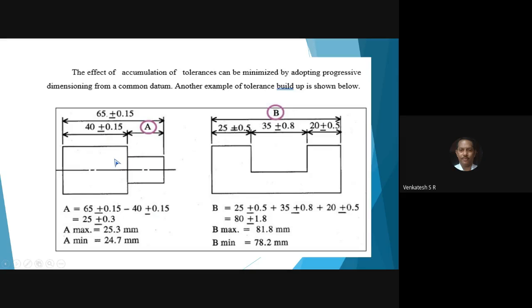You understand the process of marking and all those things. Usually, the diameter of the shaft you have to produce in the component is 25 millimeter. Actually, the raw material has 27 millimeter. Then you have to remove 2 millimeters of metal, and afterwards you have to mark the dimension on the workpiece. Then you carry out the machining operation by using lathe. Same way, you have to produce the component in machine shop.